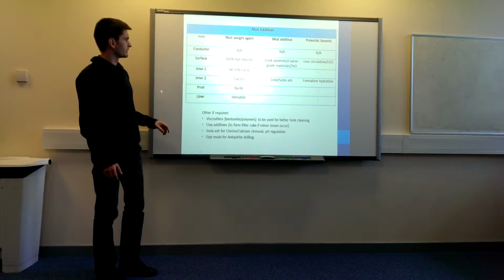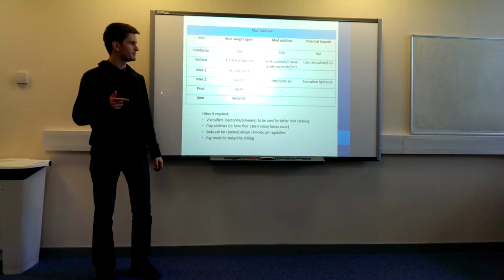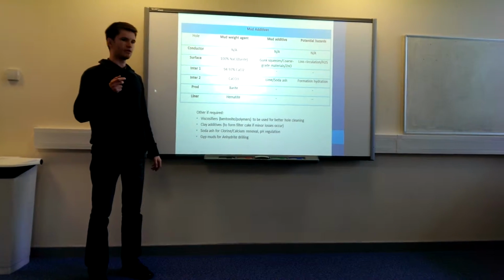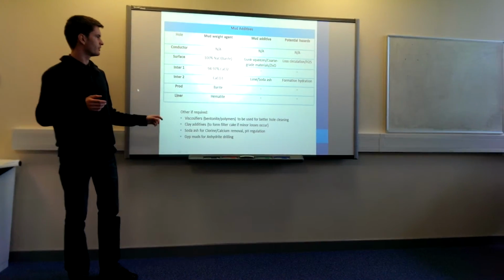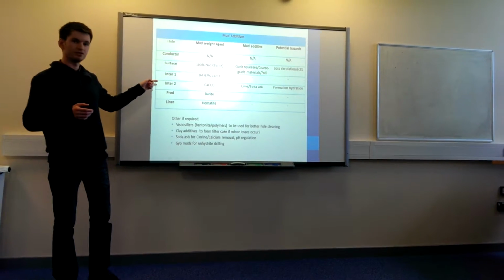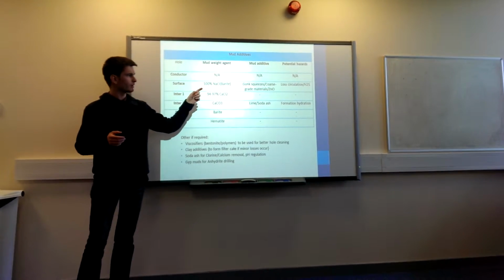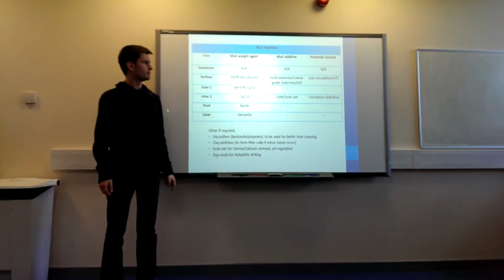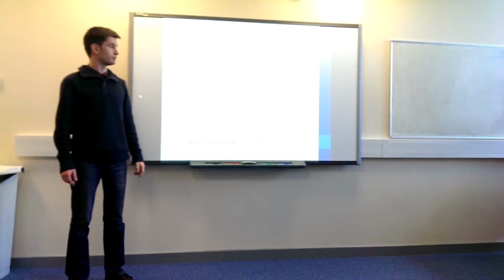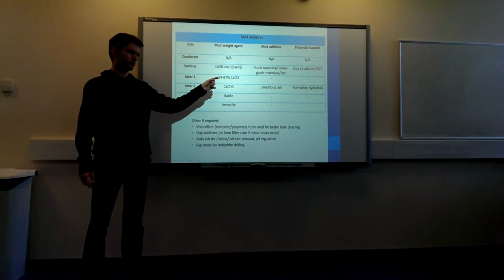After that, I considered the additives which contribute to such properties of the mud like viscosity, density, mud cake, filtration, and other hazards elimination. The main problematic zones in our well were the surface and second intermediate sections. In the surface casing section, the main problem was the presence of H2S influx and lost circulation zones, and they were combated by gunk squeezes and coarse grade materials.